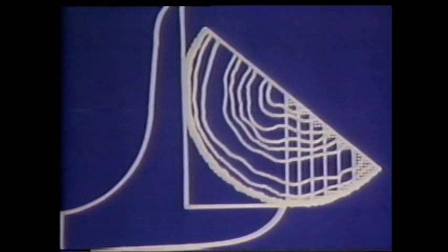Quarter sawn or rift sawn lumber is cut on a radius from the pith to the bark. Lumber cut this way looks like this. Since quarter sawn lumber results in a substantial waste, little is produced today and the cost is higher than plain sawn. But quarter sawn lumber wears more evenly and has other advantages that might make it worth the extra cost to you.